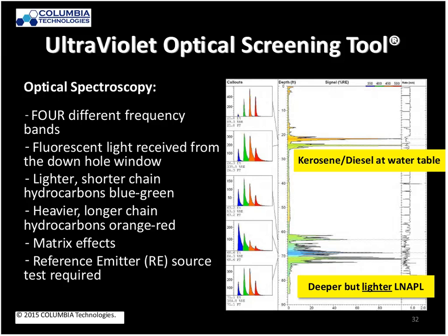I think I told you this, but this graphic is pretty critical to smashing that conventional wisdom that LNAPL floats, because here we've got a 90-foot push, and we've got an orangish-greenish response typical of kerosene at about 20 to 25 feet or so. And then 50 feet below that, we actually have a lighter blue-green response down in here. So we're smearing gasoline down here and diesel up here near the surface. Did that come from this particular source? Not known from this single log, so we would have to look at these in a systematic approach of looking at the sites.